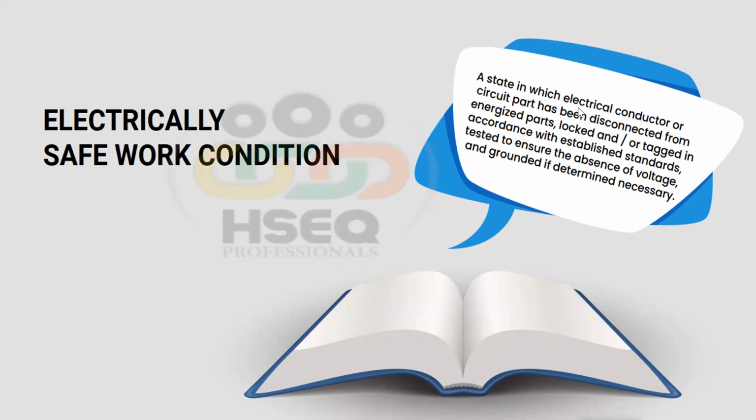It is a state in which an electrical conductor or circuit part has been disconnected from the energized part, locked and tagged in accordance with the established standards, tested to ensure the absence of voltage, and grounded if determined necessary. So we have to follow all these steps in order to finalize whether the equipment has been put into an electrically safe work condition or not.